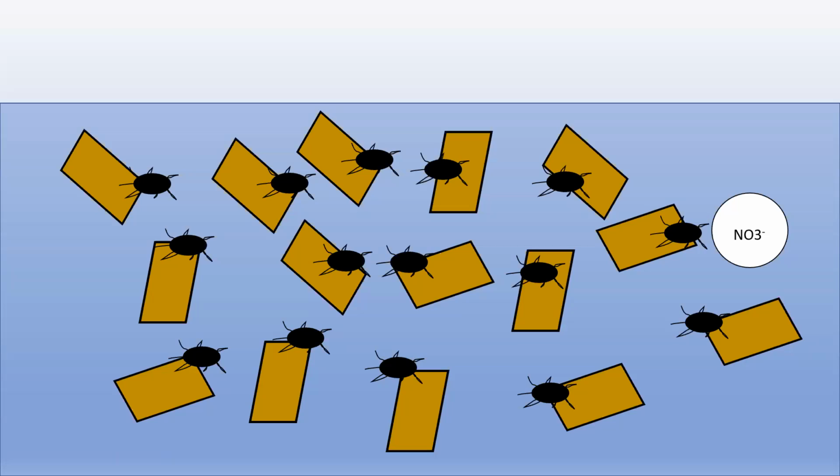Denitrification is the reduction of nitrate all the way down to dinitrogen gas, or N2. When you keep nitrate in anaerobic conditions where there's not plenty of oxygen, the bacteria are going to use that nitrate in their respiration process. And what that does is it reduces it sequentially to several intermediates, but the final step, and hopefully we get to that final step, is to get it to N2 gas. That N2 gas, that dinitrogen gas, just gases off into the atmosphere.